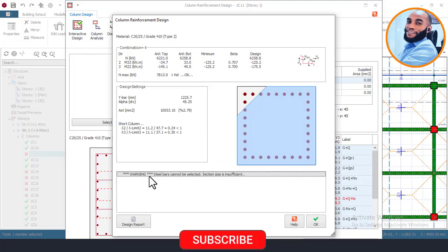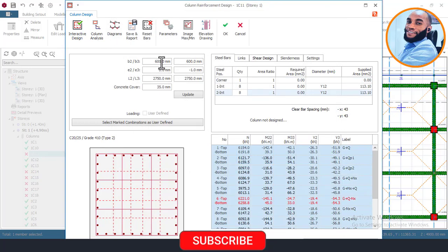Okay, now on this one it shows the warning that steel bars cannot be selected. Section size is insufficient. That means the size of this column here is not sufficient. So I'll have to come here again. Let me increase it to 650 and see if that will be okay. 650 by 650. You can choose to use a rectangular column if you want. Okay, and I'll make that 0. And I'll come here and click update, and then click on reset bars.